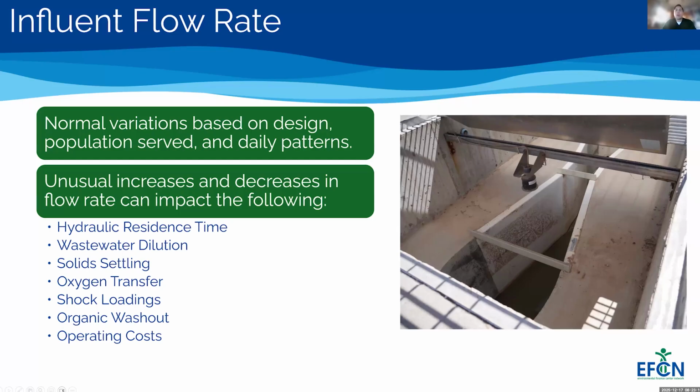So, if we have increased wastewater, how can we adjust? We would try to slow down our detention time in other processes, possibly. If we have a redundancy or an equalization tank, we can maybe store some of that water temporarily. We may increase oxygen so we can increase the rate at which we're treating wastewater. So those are a couple of solutions when we have increased wastewater.